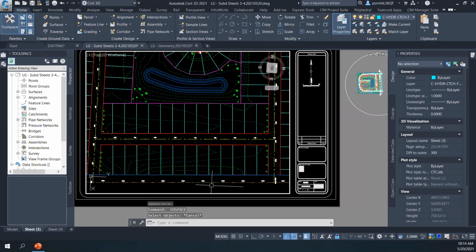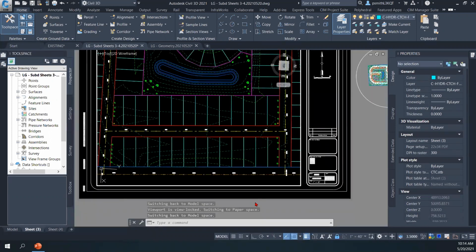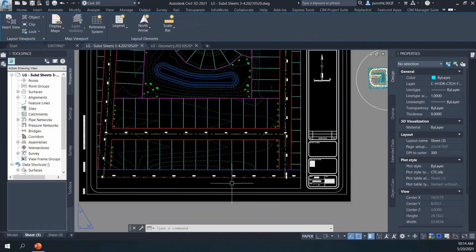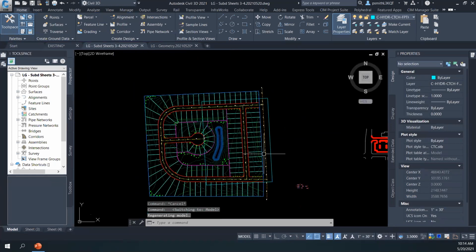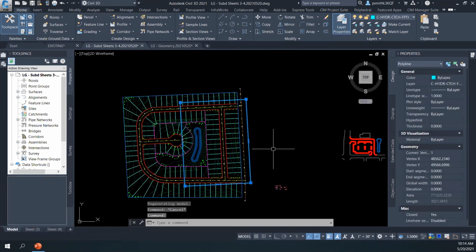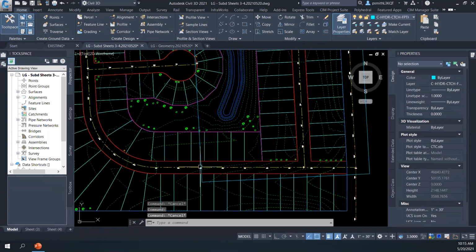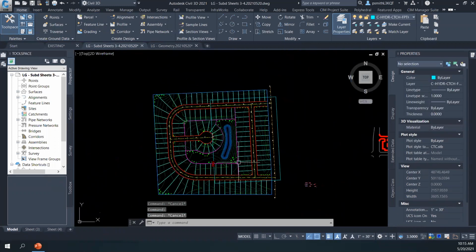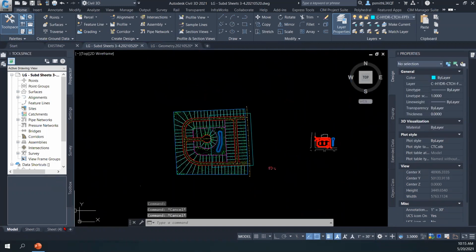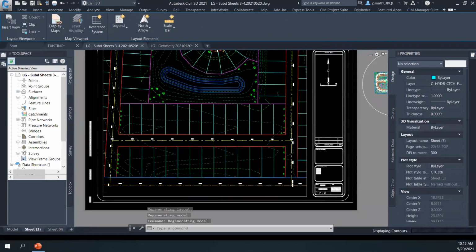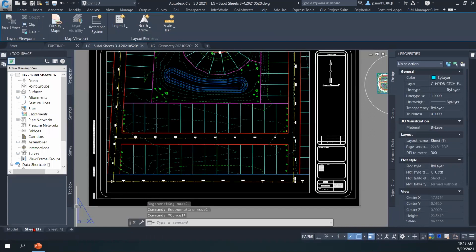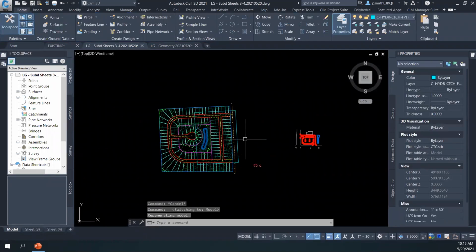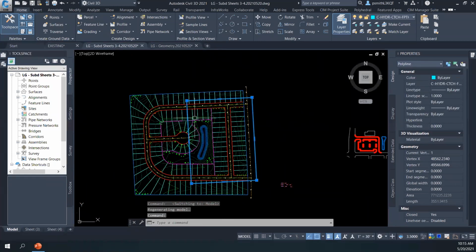All right. So once that's done, I'm going to double click. It's going to have that viewport activated after you're done with that. Now, if you go to model space, there it is. This is going to be the extent of where your match lines will be set up exactly, depending on the size of your viewport. If this was a different size and you traced over top of it, then you change space again, that would show you exactly where your match lines would be.